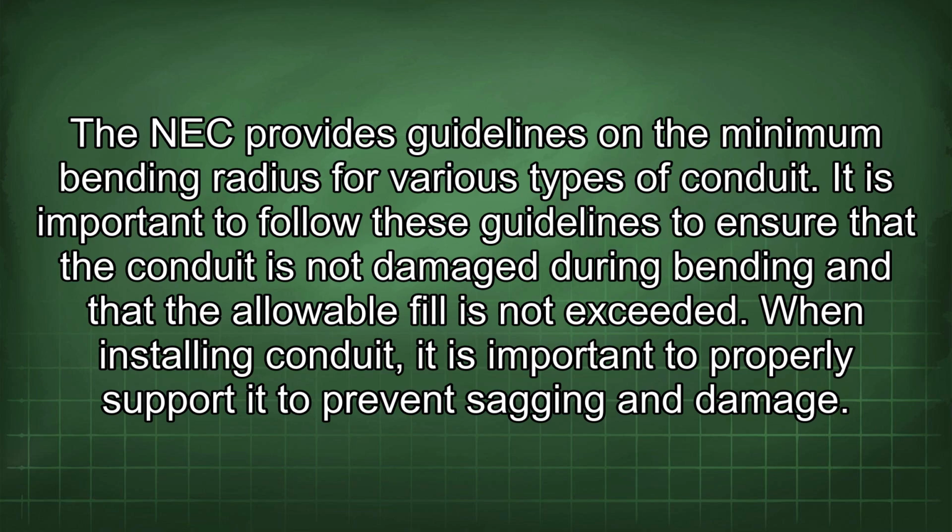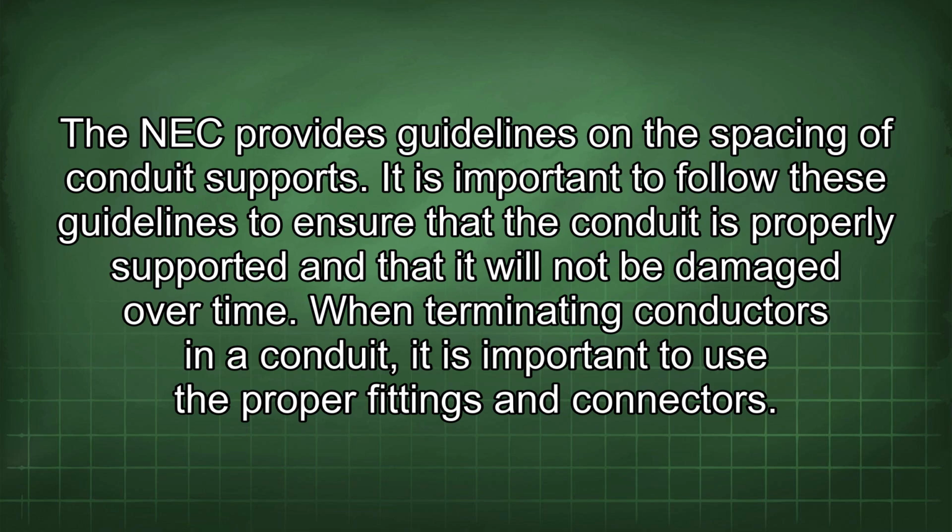When installing conduit, it is important to properly support it to prevent sagging and damage. The NEC provides guidelines on the spacing of conduit supports. It is important to follow these guidelines to ensure that the conduit is properly supported and that it will not be damaged over time. When terminating conductors in a conduit, it is important to use the proper fittings and connectors.